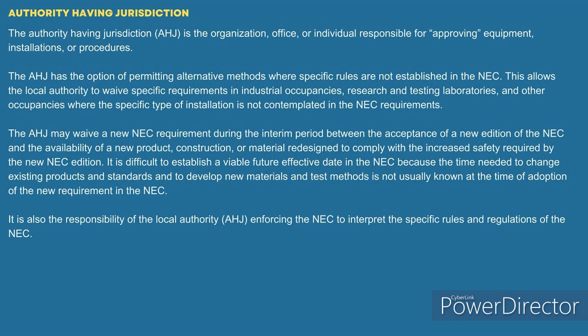It had the AC unit with the disconnect right above it. The whole thing was, Andrew, that disconnect was not likely to be worked on energized, because you could go to that breaker, kill it, verify it's de-energized, and then work on it safely while you're sitting on top of the AC unit. You don't require that 3-foot working clearance.